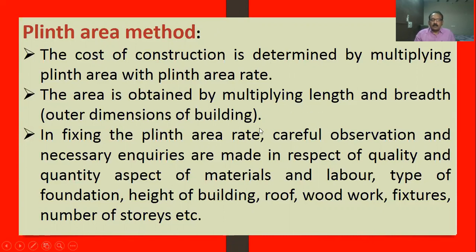See, there are some rules and regulations. There are limitations and inclusions in this plinth area method. In fixing the plinth area rate, careful observation and necessary inquiries are made in respect of quality and quantity aspects of material and labor, type of foundation, height of building, roof, woodwork, fixtures, number of stories.